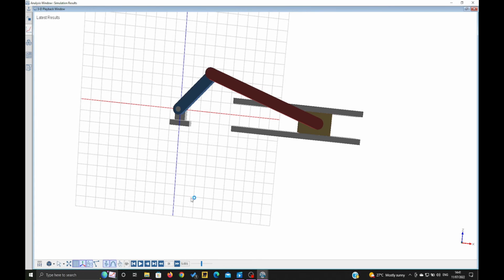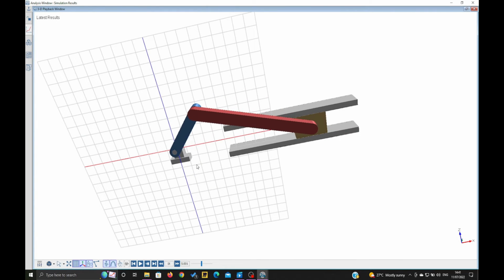The reason behind is that we have not grouped the ground linkages properly. So the linkage that the mouse cursor is hovering at, the link 1A and the link 1B, the slider link to the ground, has not been grouped together and then grounded. So what we can do right now is we will group both the links together and then we'll attach a ground to them. So let's do that.